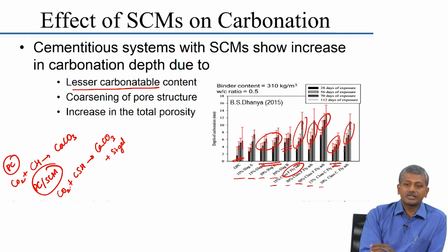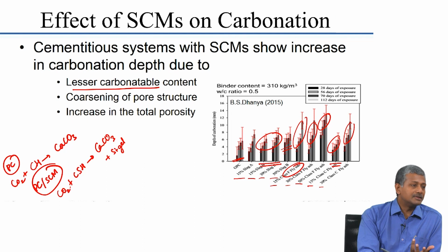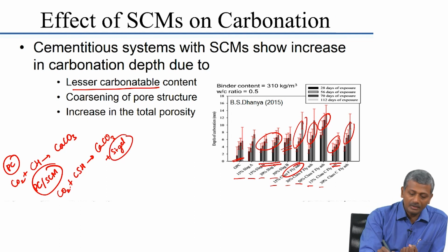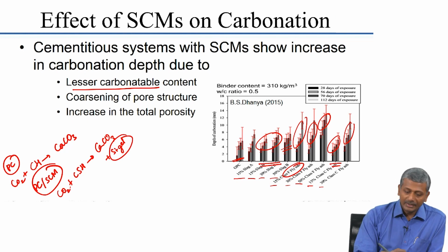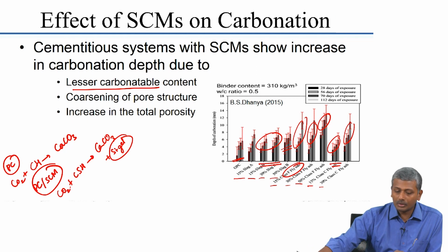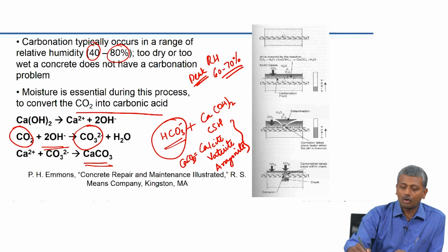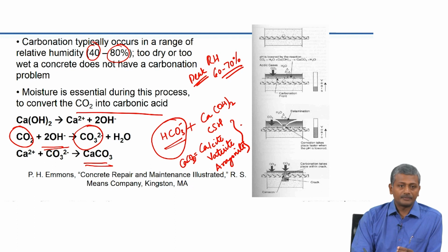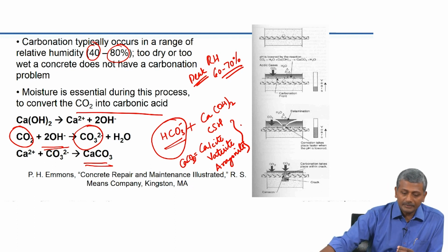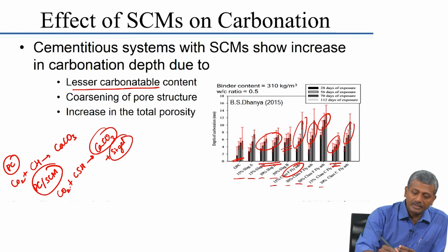The silica gel, just like what we saw in the case of sulphate attack, tends to be non-cementitious and porous. So, that is where the porosity of the system is getting increased. And further, in the last slide I talked about the fact that calcium carbonate can form in different crystalline forms. Okay. The overall space occupied by these different polymorphs is quite different.